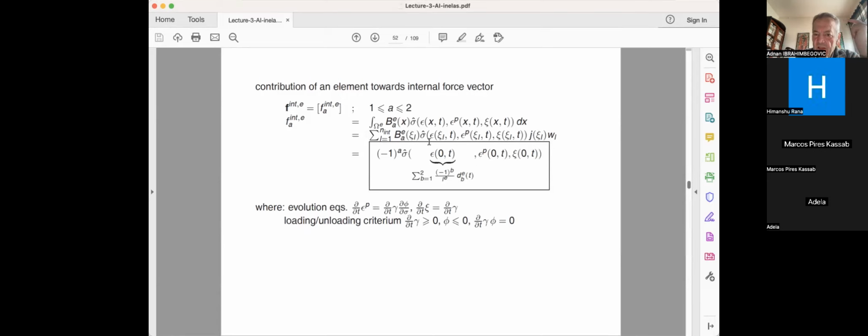And then basically that amounts to saying that I need a total strain in the center of the element. This can be computed from my interpolation for xi equal to 0. That's the same as in elasticity. And on top of that, I have to store the plastic deformation and hardening variable in the center of each element. So typically, these internal variables are computed only locally at a particular Gauss point of an element that we are interested in. The element which plastifies now has to have the possibility of storing in the database the plastic deformation and hardening variable, and then you can carry on the computation you might need.